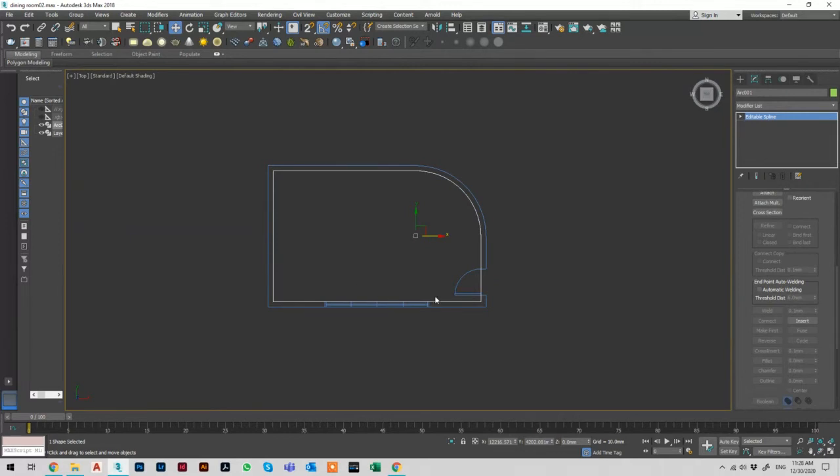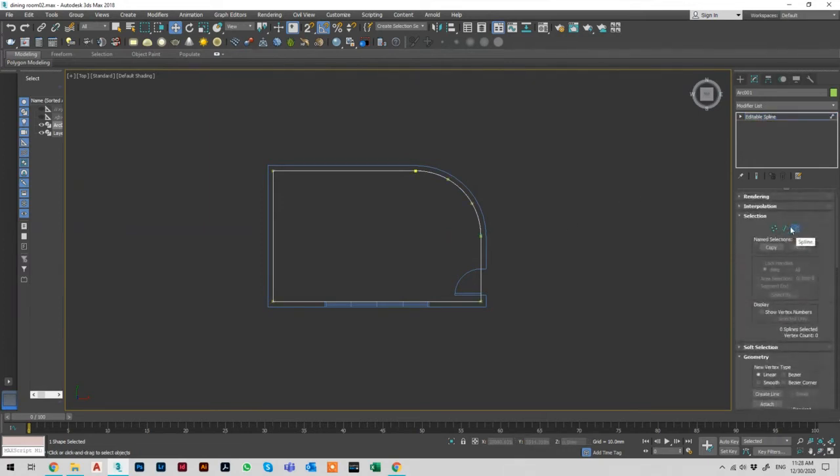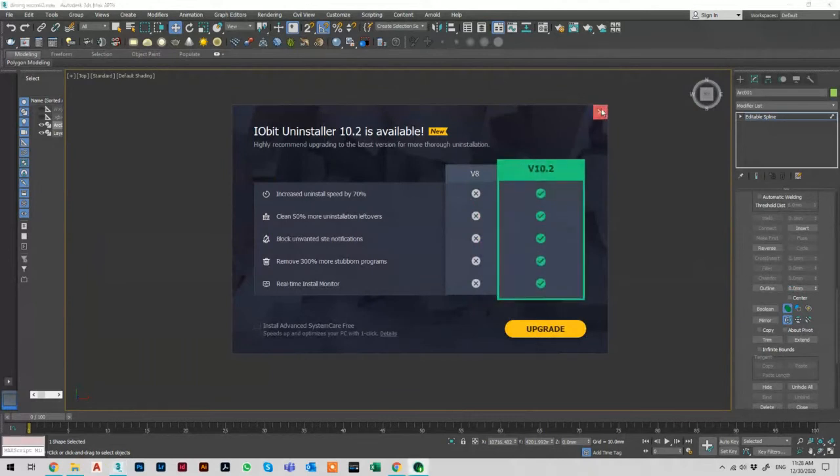Now the second thing that I want to do is to make an offset towards outside. So in this case, I will go to 3, which is the spline itself. After you select spline, you'll select this line here, which is now all one line. Go down to outline and then type here, for example, 200. This will create an offset towards outside.